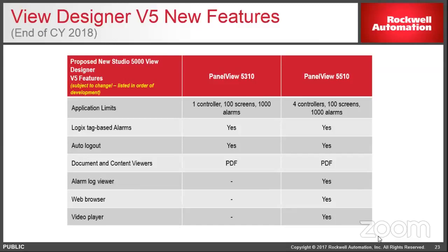Where traditionally in a PanelView 7 world, we're able to go natively using Kepware that's built in. In this product, we would bring those data points in via the controller and use either a DIN rail mount or in-chassis module to be able to convert that.